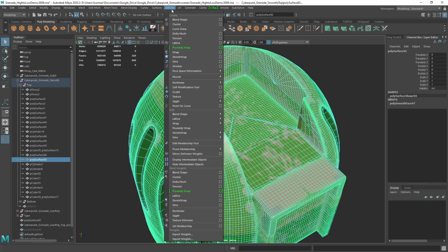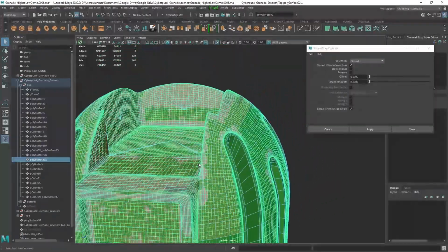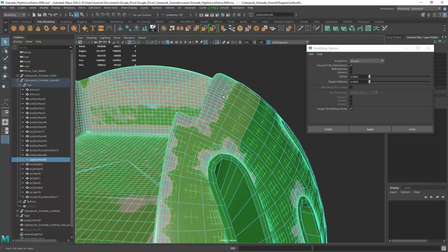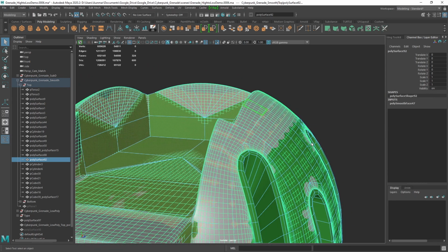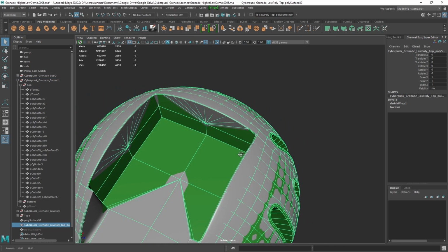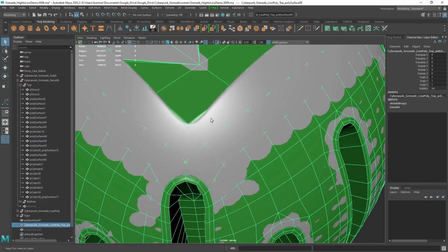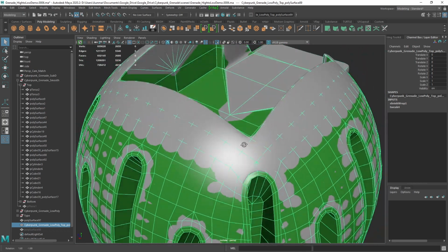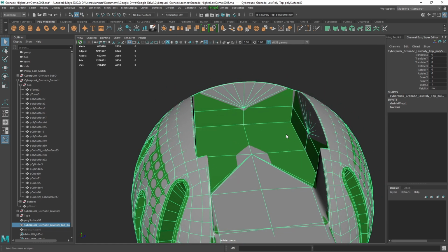This is where you can use the deform and use shrink wrap. These are typically the settings that I use for shrink wrapping, and what this is going to do is help make sure that it wraps on this mesh here. I typically use projection and these settings, and then hit apply and take a look at that. Now it's wrapped itself around the mesh, and this is going to be very, very helpful. There are a couple of areas that I do plan to go back and cut in some detail to help with these corners here, especially being on this highly visible part. So I do plan to fix that, but at least you get the idea of how to use shrink wrap.